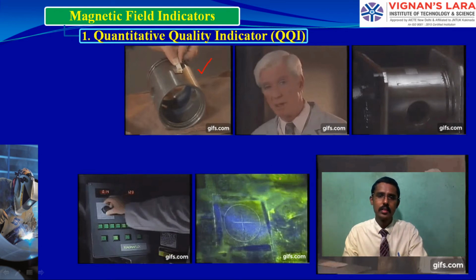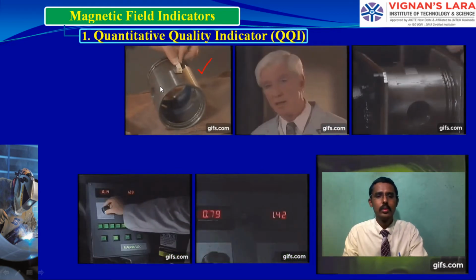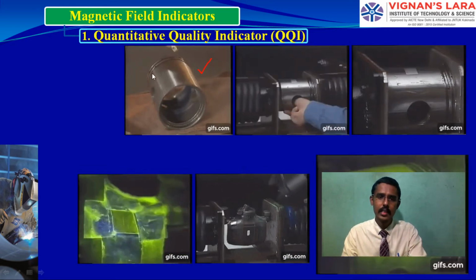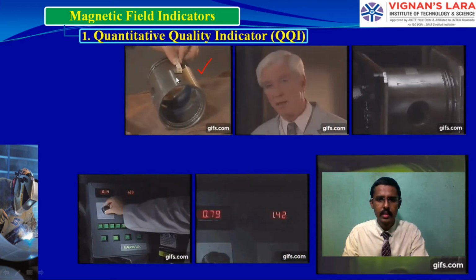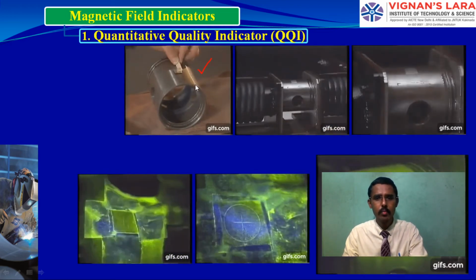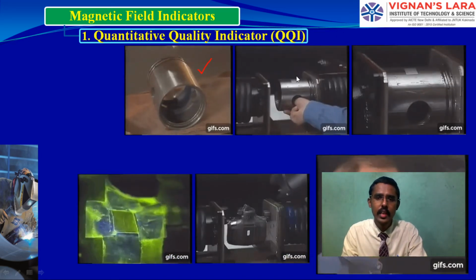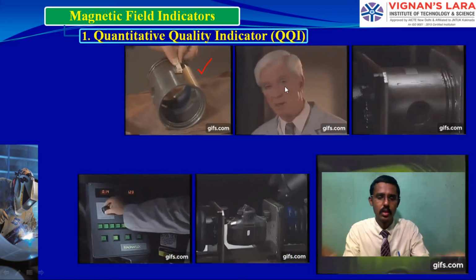Then what happens after doing such placements? I want to pass the liquid, which means wet particles. You see, the color changed slightly. In this first GIF, it is playing. Here they are placing the strip. In the second one, after placing it on the same specimen for inspection purposes to find the discontinuity, they are placing it in a horizontal setup, a longitudinal horizontal machine setup.